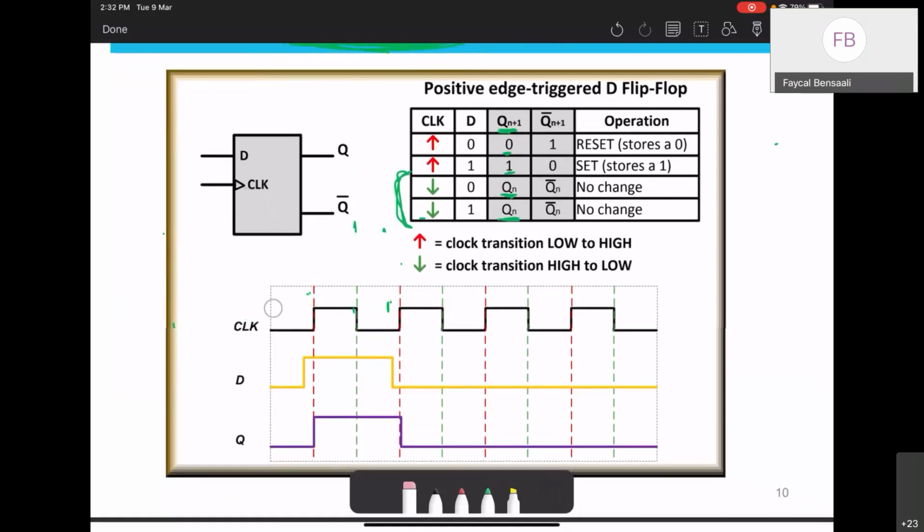Let's say that I have this flip-flop, and these are the waveforms. Do you understand waveforms here? Yeah. So this is the clock. It's 0, 1, 0, 1, 0, 1, 0, 1. And let's say that we have this input D. So D starts like this, it's 0 for this time. Let's say that this is 5 nanoseconds, this is 10 nanoseconds, this is 15, and so on.